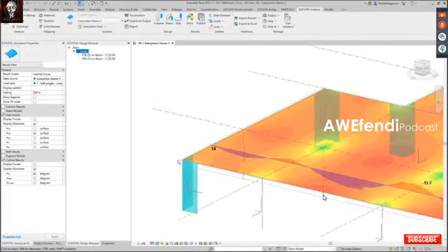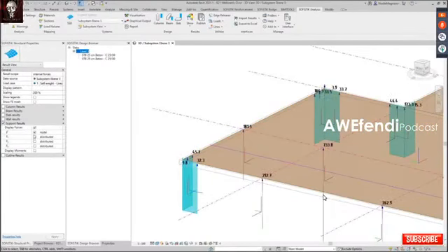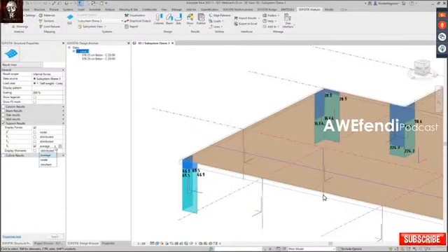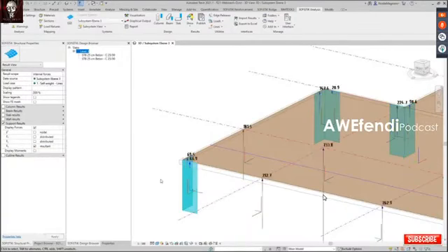And what is interesting for subsystems, you can also display support results. And we are talking not only about main system supports, we are talking also about subsystem supports. So you can see here the resulting forces on the top of my support elements, which are represented by the beams, the columns and the wall in different styles. So average, distributed, or even resultant for the complete member. And here you can see it for the linear load cases, but also for the combination, because I analyzed it, so it's in the CDB, so the information is here.